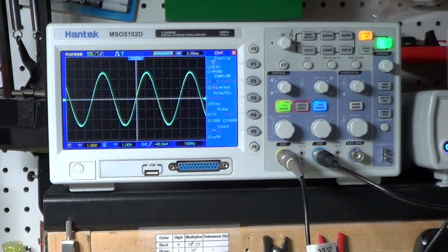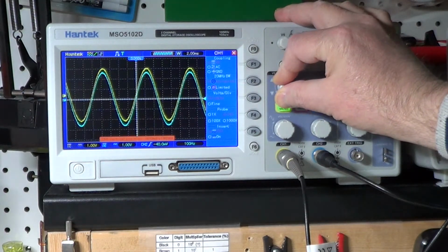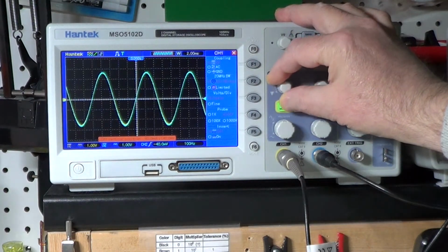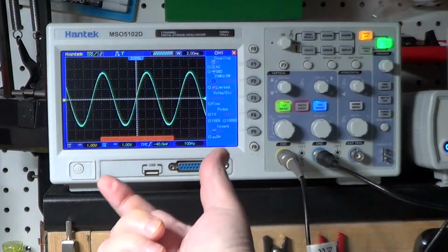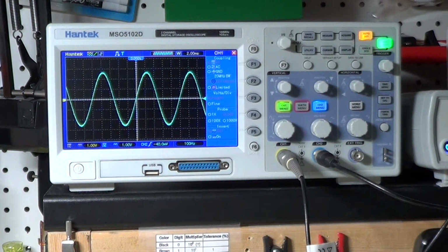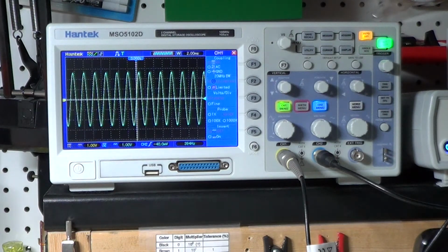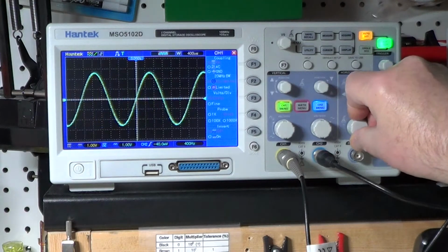Okay, here we are very low, and let me move this so you can see what's going on. You see there are two signals that are practically identical. I just superimpose them so you will easily see how the amplitude and the phase shift change simultaneously. Now I'm gonna increase, like I did in the previous video, the frequency a little bit at a time. And I'm gonna keep adjusting also the oscilloscope to change the scale so you can see better what happens.